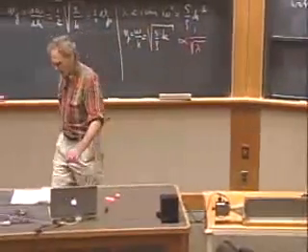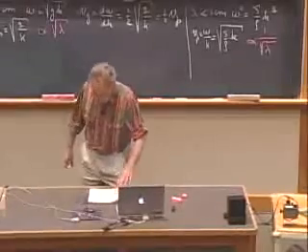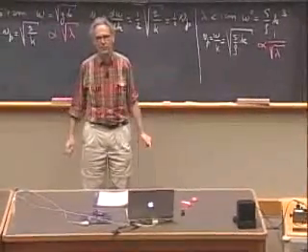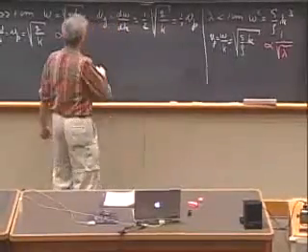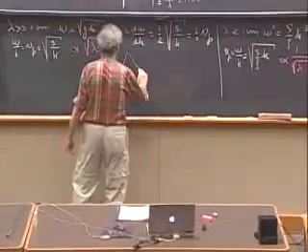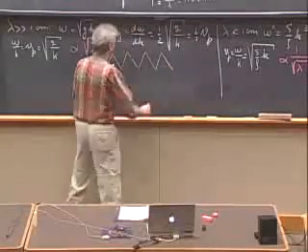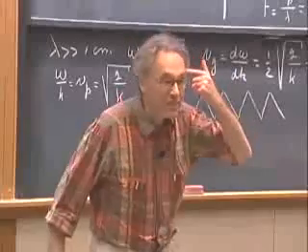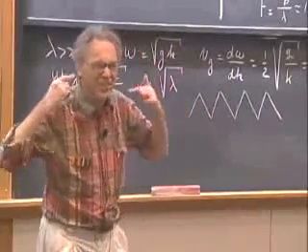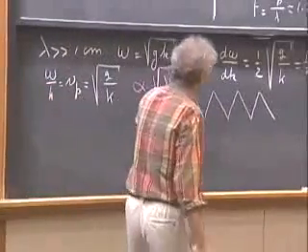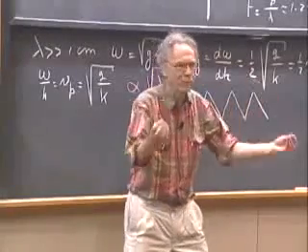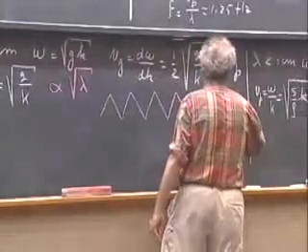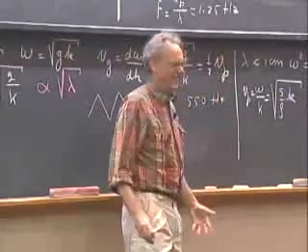We modulate the 10 gigahertz with a nasty triangular sound of 550 hertz. The reason why that is nasty is that anything modulated triangular requires high harmonics, because think in terms of Fourier space, and higher harmonics are not so nice in your ears. If this were a nice sinusoid, you would hear a beautiful 550 hertz tone, but because we modulate it with a triangle, it's a nasty tone.